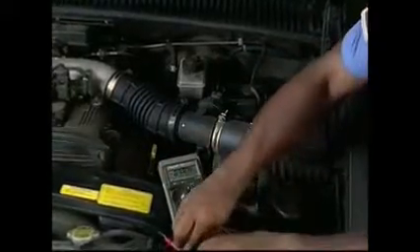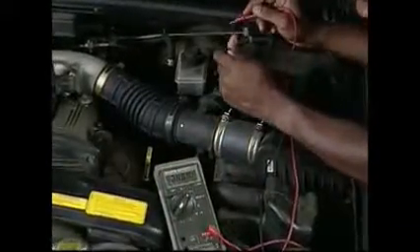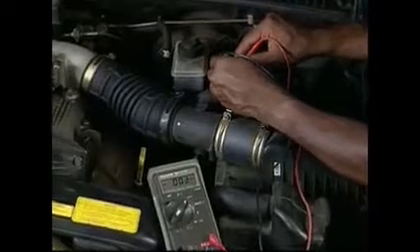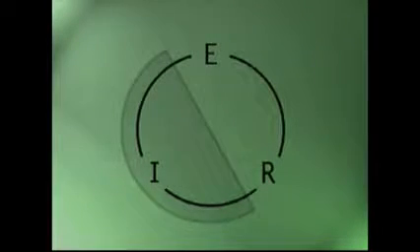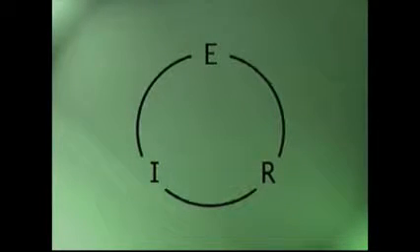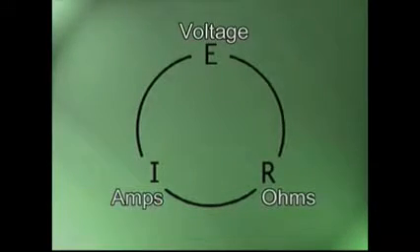The digital multimeter is your way to get the values of the voltage, amperes, and ohms in a circuit. These measurements will allow you to determine if the circuit is operating outside specification. If the circuit is operating outside of specification, we'll need to diagnose why the values for either voltage, resistance, or current have changed from the original specifications.